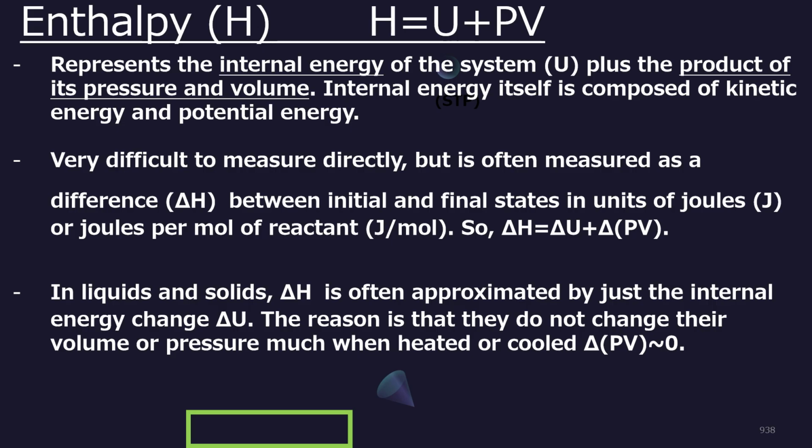One thing I will say though, one of my students did their EE on hot oil near its smoking or flash point. So he was heating oil up to like 250 degrees Celsius. He filled the beaker up 2/3 of the way, but when it got to 250 degrees Celsius, it actually started overflowing. So depending on your material and your amount of temperature change, you might actually have significant volume changes, which means you wouldn't be able to use this simplification. So just be aware of things like that.